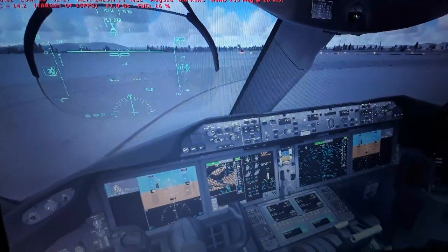We have runway 14 in Zurich International Airport, the LSZH in Switzerland, so we can use the onboard frequency receivers of the antennas for the horizontal localizer and the vertical glide slope, so we can align with the runway magnetic heading of 136 degrees. We have also the flight director crossbars for manual guidance of the aircraft and the autopilot crossbars for automatic guidance of the aircraft. We have also the angle of attack of the aircraft as it flies in the flight mode and zero with the autopilot and the autothrottle, lateral and vertical navigation mode.